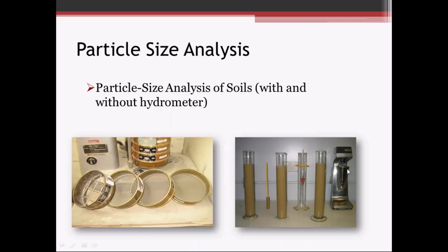Particle size analysis, there's basically two components of this test. The first component is to run the sample through a series of screens down to a number 200 sieve, which has square openings of 75 microns. And that'll determine the percentage of sand and gravel in the sample.